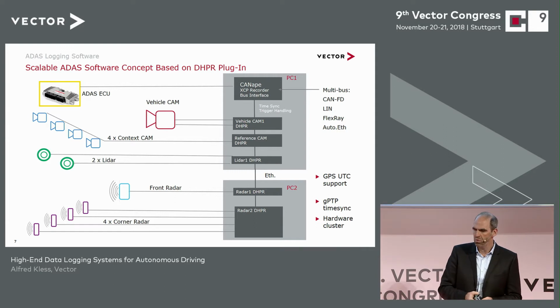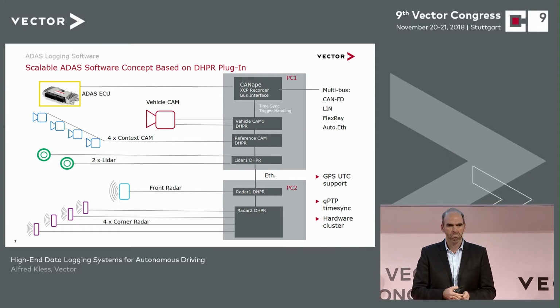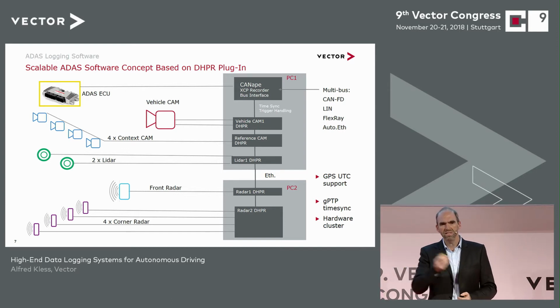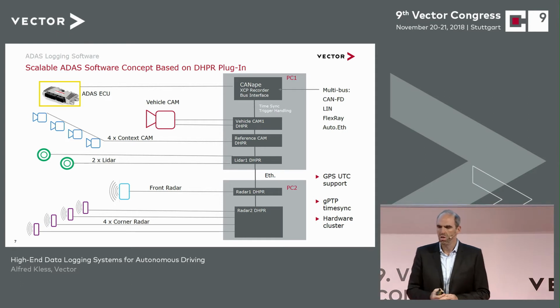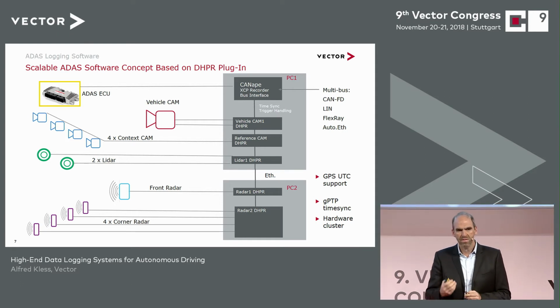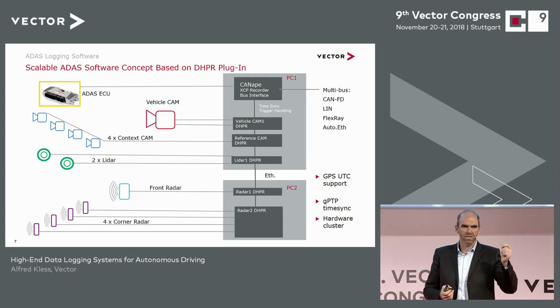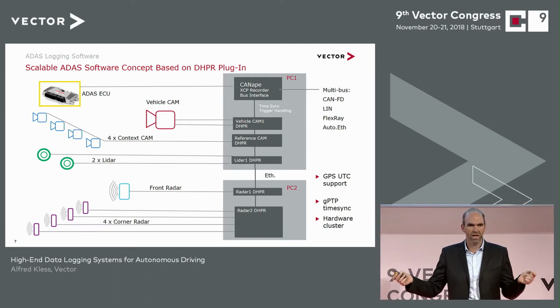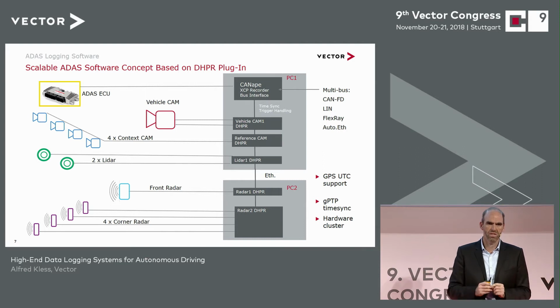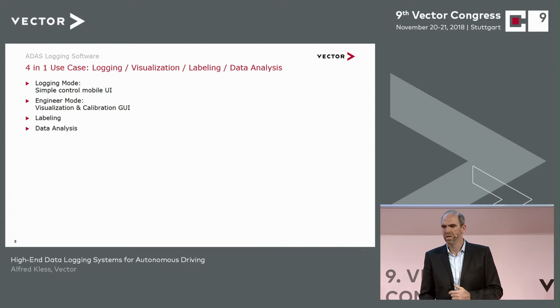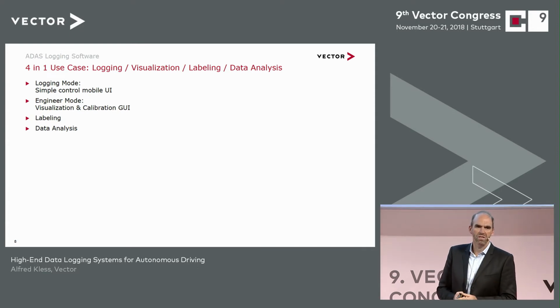The other thing that we have is time synchronization via GPS, UTC time. So if you have a platooning application in a truck, for example, where two trucks are driving, I cannot then lay an Ethernet cable. For that purpose, we use the GPS time, and we take the measurement time from the reference time of GPS, and so even two PCs that are not physically connected can be measured with synchronous times.